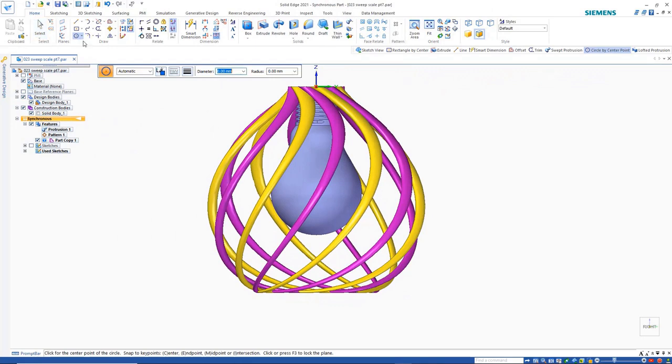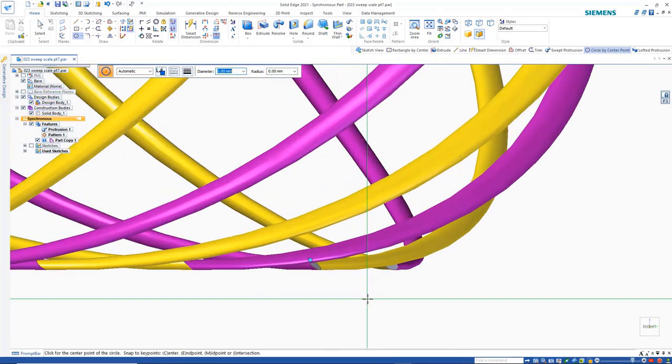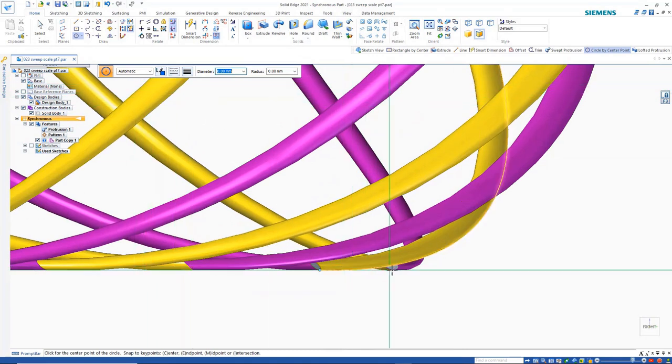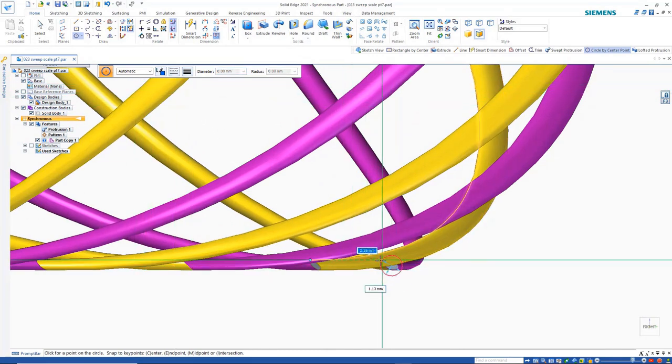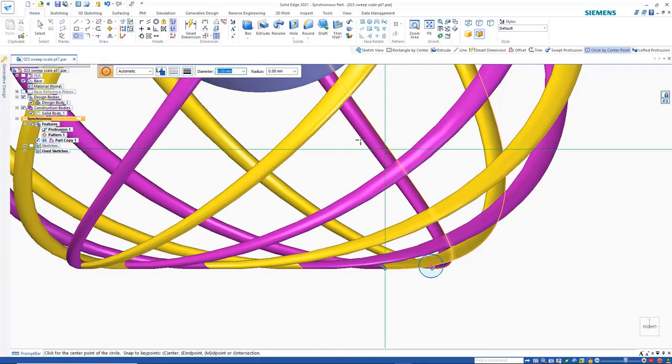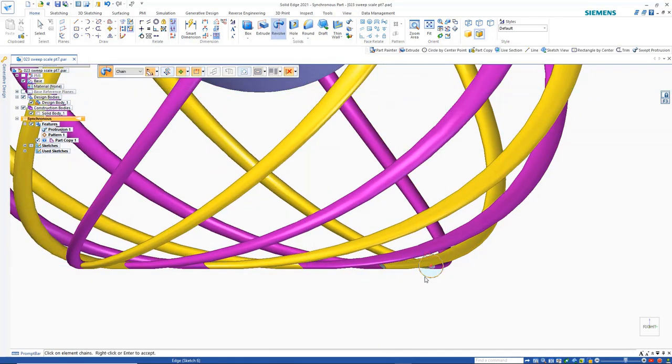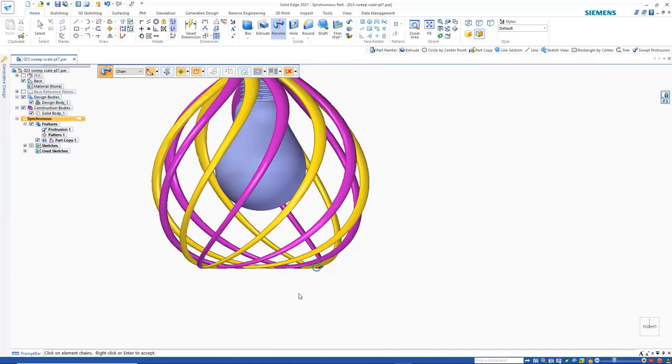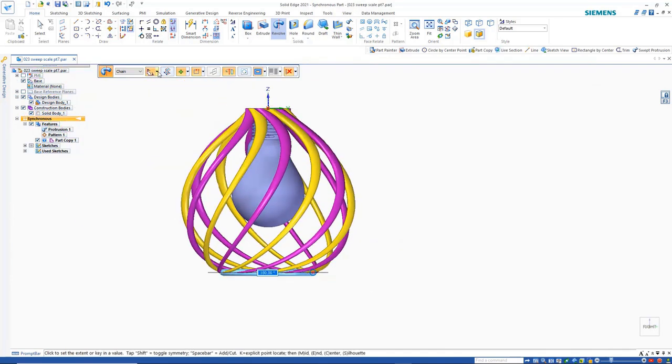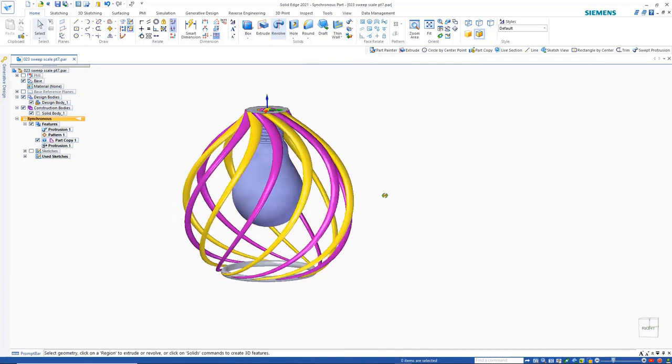And again, the last thing you may want to do is come back and just lock to the YZ plane and come down and add a circle somewhere or any shape just along the bottom here. And maybe this is a little too big, but just run with that and do a revolve around the z-axis and close it off at 360.